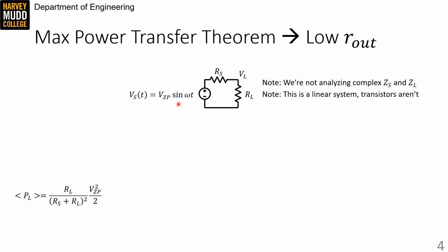But we build amplifiers out of transistors which are wildly nonlinear. And even worse, we won't be able to use our usual dodge of retreating to small signal analysis to make our amplifiers appear linear, because we want output stages to deliver really high power. And delivering really high power usually means really big voltages and really big currents, so small signal analysis won't work well.